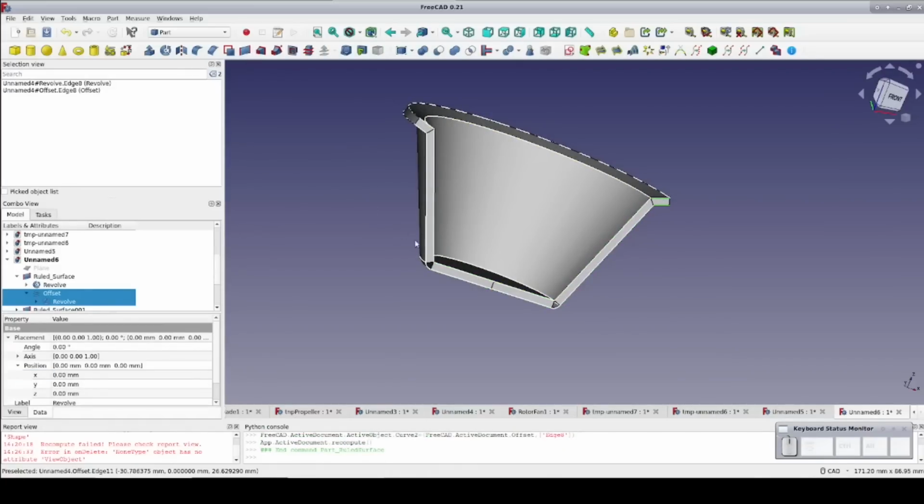We filled in between all of the edges, but you'll notice here in the corners we have 2 spots where the shell is open. This is where the problem happens. We need a surface to fill in between the 2 lines and an arc. The part workbench doesn't have a tool for that, and that's why checking the fill box failed.